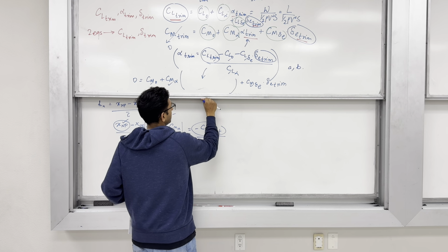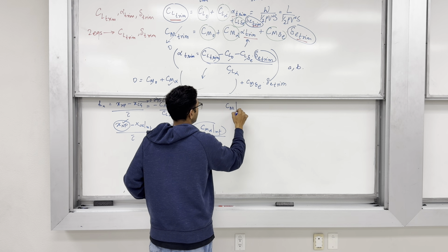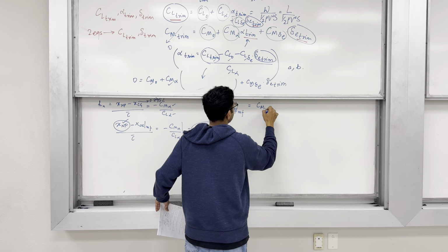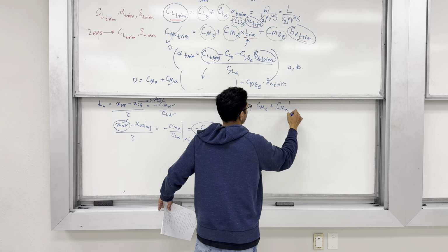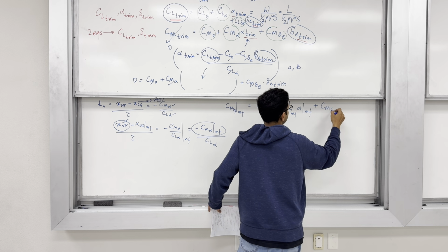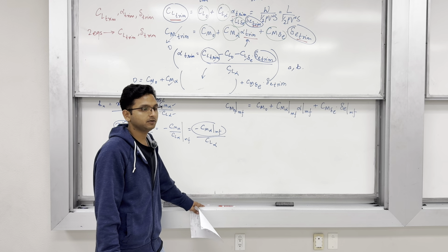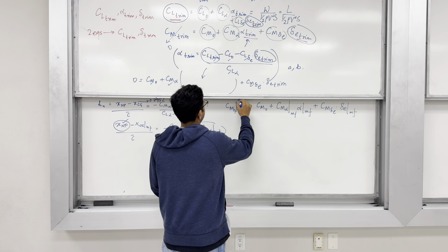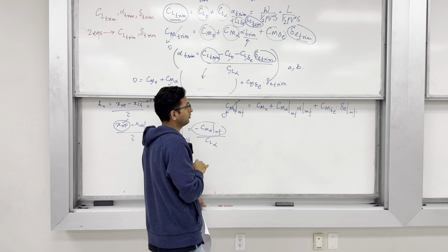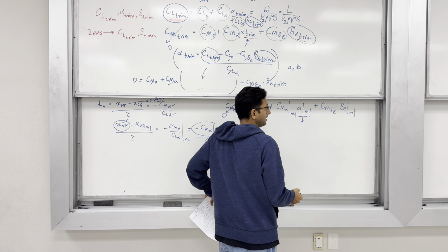For this, let me realize what is happening at the most forward configuration. So, CM about CG most forward, in the most forward configuration, we have CM naught plus CM alpha most forward times alpha most forward plus CM delta E times delta E most forward. Now, when does the most forward situation for the CG happen? At landing. So, I know that I am flaring and I am trimming. So, this is going to be 0, the total moment on the aircraft. Alpha most forward, at that time I am flying at low speed, I need maximum lift.